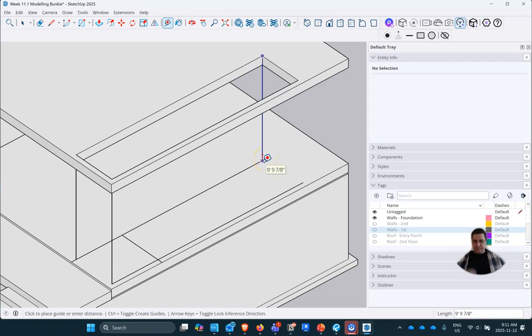That's a wonderful number. And so that's the height of our stairs there. It's almost 9 foot 10. And with stairs, theoretically, the code states that we can't have more than a 1/4 inch difference in step height from top to bottom. You could say that 1/8 is negligible, meaning it's something we could ignore. But we don't want to really plan for that, to be honest with you. So let's go 9 7/8.